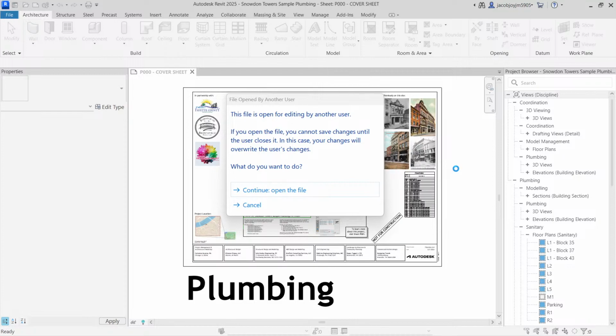So key plan, everybody will prepare a key plan. If it is an architect, then they highlight architecture matters. If it is an electrical department, they highlight electrical things. If you are a structural guy, then you have to mention the boundary and the foundation, the distance between the foundation edge and the boundary line. Those kind of key information you have to mention. And you should be showing the north direction also.